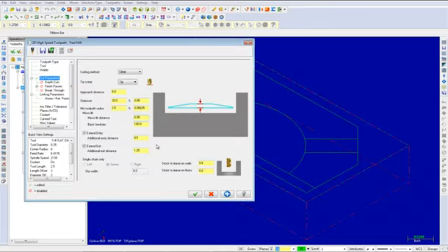I will now take a brief moment to explain a few of these parameters. Step over sets the distance between adjacent cuts of the toolpath. Min toolpath radius defines the radius of the arc that the tool follows along its semicircular path. This value must be greater than the step over amount. Micro lift distance is the distance the tool lifts off the part on back moves.